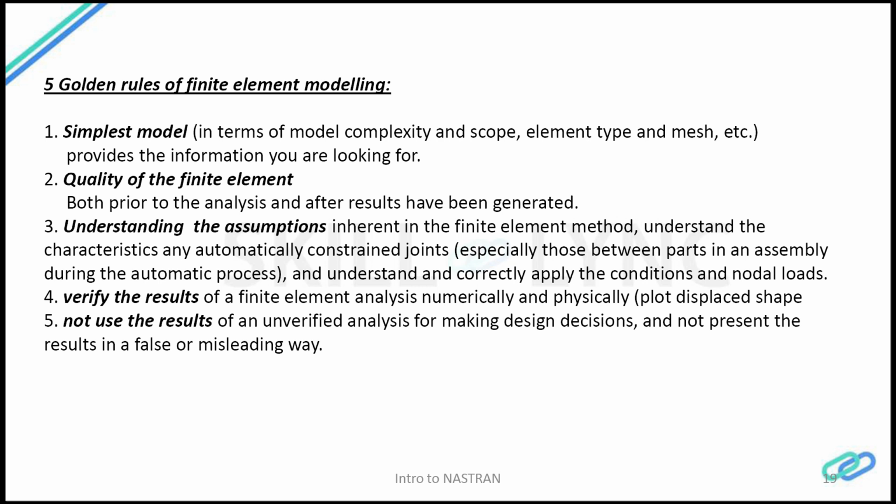Then select the proper element types, the number of elements and the mesh, and also look at the information you are after. You should understand the model and the function of the geometry that is being given.